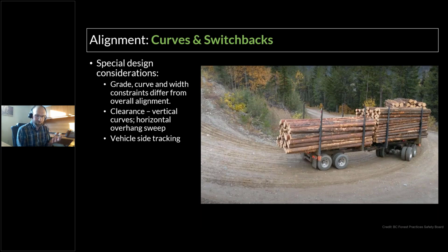To account for visibility, there are tools in the software for that as well, but the big things you want to consider are sight stopping distance. That's going to vary by design speed. It influences what curves to use, and it may require you to remove visual obstructions if you need to see a certain distance ahead. And in line with that, pullouts are important.